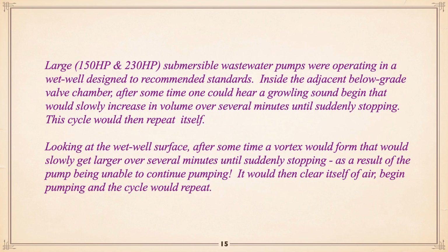Now, case situation. Anytime you see purple, it's a war story of mine. Pump station on Vancouver Island had a 150 horsepower pump and a pair of 230s, in a wet well designed to recommended manufacturer standards. Inside was an adjacent below valve chamber. And if you're in the valve chamber, after a period of time, you'd start hearing a growling sound. It would suddenly quit. And then a few minutes later, you'd hear the same thing all over again.